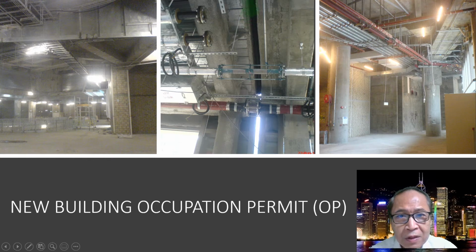You see here, you see a big gap here. Why is there a big gap? Because these are two different buildings, with an expansion joint for the movement. This is the two buildings here. During storm time, there is water leakage, so there should be a water tray here, something like that, a water tray to receive the rainwater. You see the pipes have got the expansion joint like this. This is for the movement, to accommodate the movement.